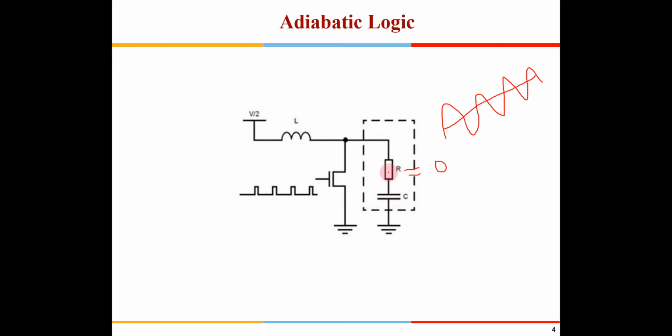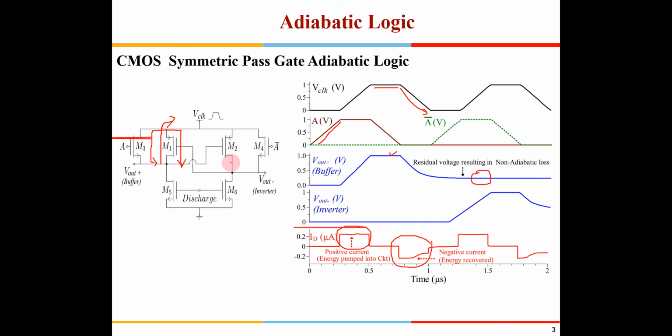time, right? But because of stray capacitances and stray resistances which come into the circuit, because of the inductor and layout, and also we are not able to recover back 100% of whatever charge we are giving into the adiabatic circuit. Some of that gets blocked in the circuit because of this PMOS out here, right?